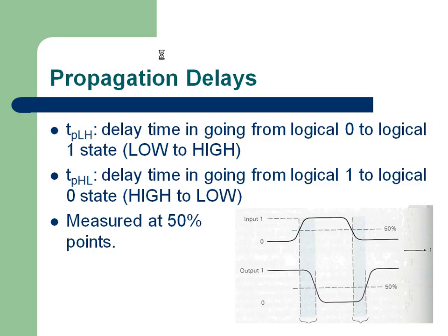There is an important point from here. I am making a reference for the next module we are going to discuss. When we say there is a NAND gate delay, precisely we cannot give one number. Because this NAND gate may be driven by another NAND gate, which may be driving only this NAND gate, or may be driving another 1 or 2 NAND gates in parallel. If it is driving 3-4 NAND gates in parallel, this may take 10 nanoseconds. If this NAND gate is driving only one NAND gate alone, it may take only 5 nanoseconds.